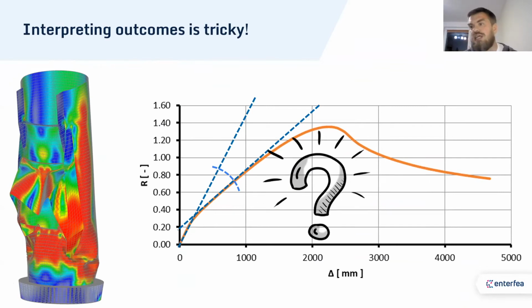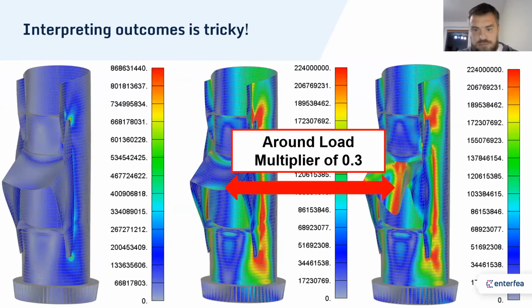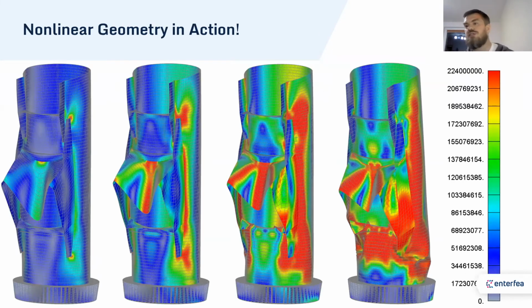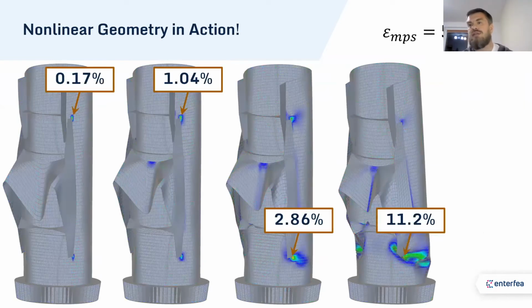So nonlinear FEA give you a powerful tool that actually allow you to not only just analyze things and see what's going on, but also to really pinpoint weird things. And I would say that that's a good way of doing nonlinear FEA. So you can see here that this is how the stresses look like. You already know that you want to look also on plastic strains, but note that I can tell you that the failure is the third one from the left with 2.8 plastic strains. Those plastic strains would still be allowable.